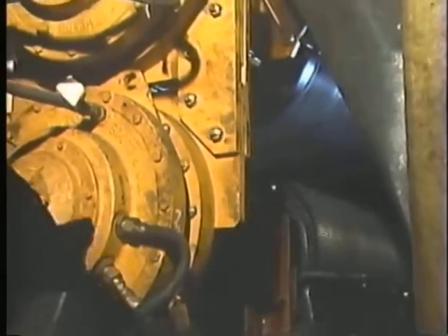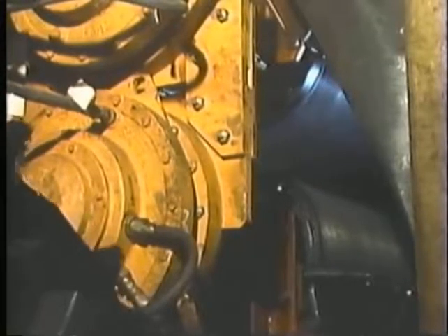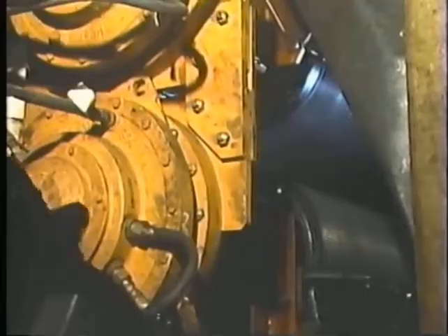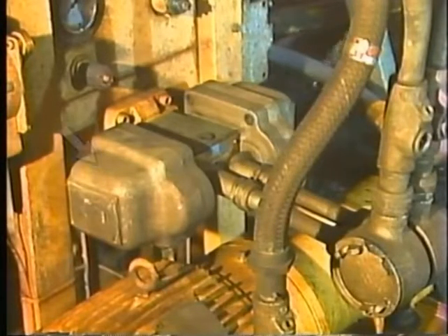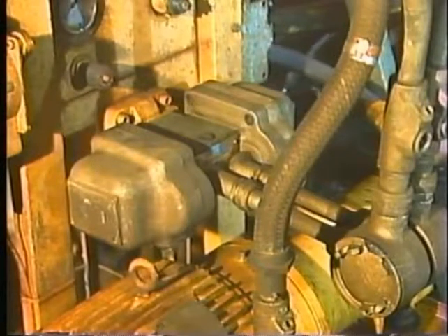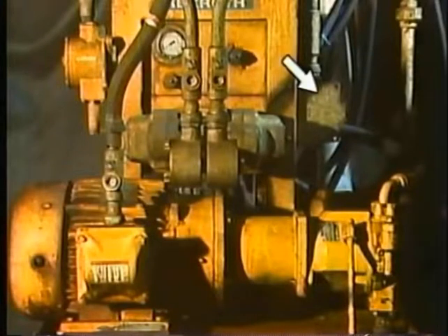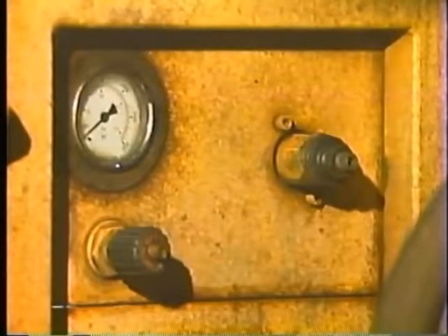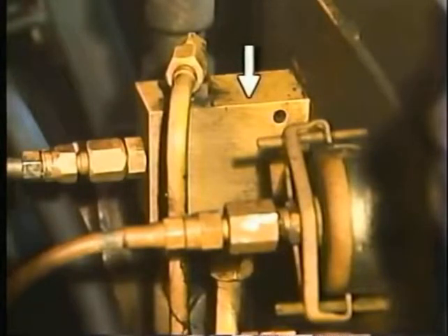Now, to rotate, raise, or lower a load, a way of controlling the direction of a hydraulic motor and actuator movement is often needed. This is usually done with a directional control valve. In many cases, it's also important to control how fast the load is moved, so a flow control valve, such as this one, may be used. Finally, since many hydraulic systems can be damaged if fluid pressure gets too high, some kind of pressure control valve, like this relief valve, is often used to prevent overpressurization.